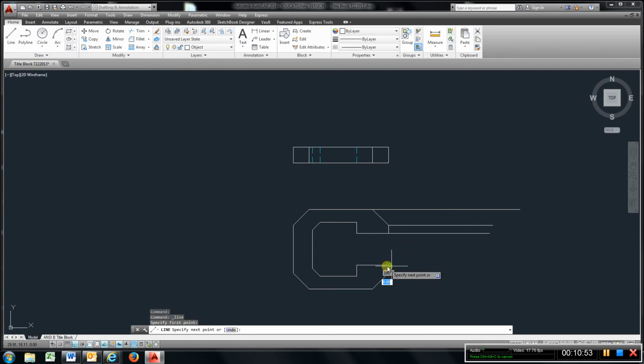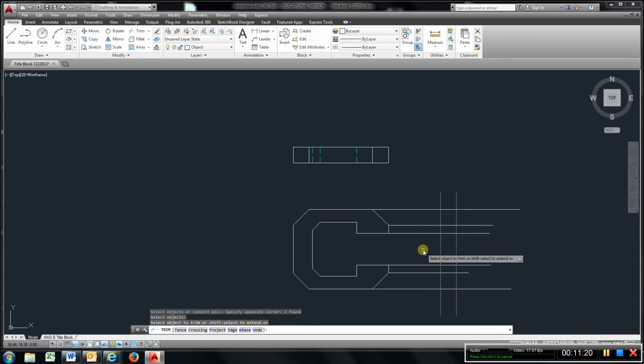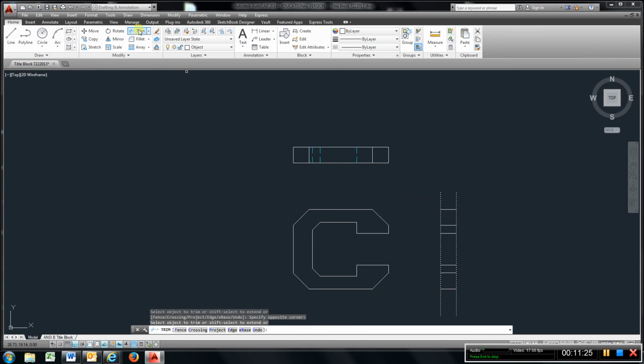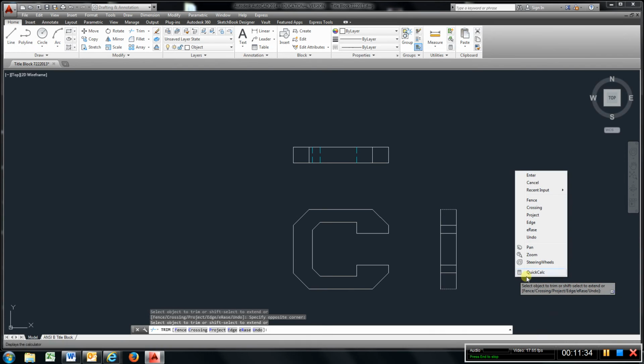I'm going to choose all my object visible lines. These are what we can see. Go up here, we have one line, bring it down, offset it 1/4 of an inch, hit enter, bring that over. Go to trim, choose these two lines, left click it, then right click, then left click by selecting everything, left click. Okay, trim again, trim off the two top and the bottom, right click, left click, left click, enter.